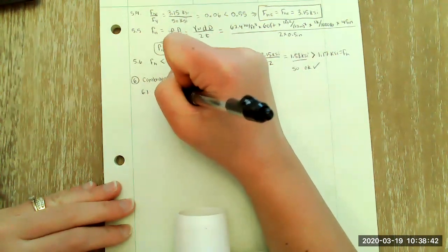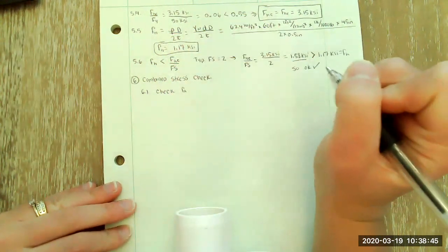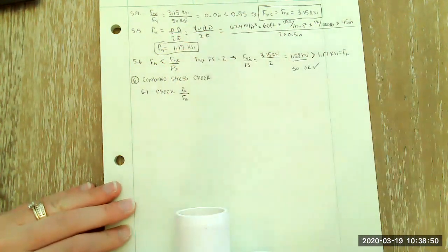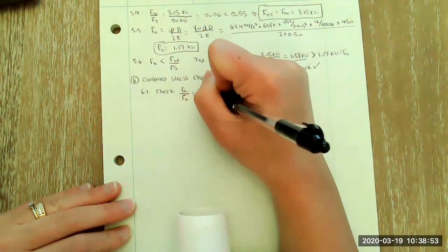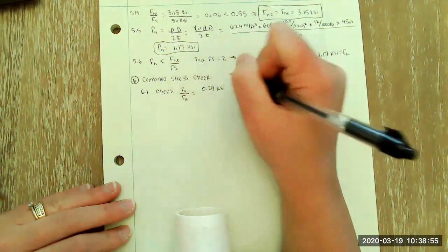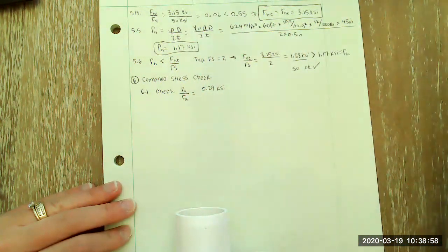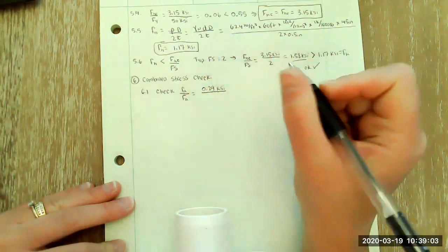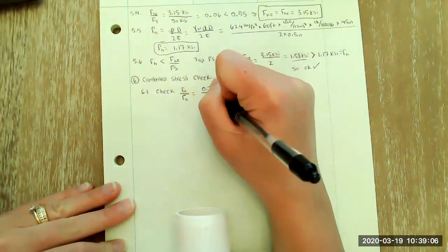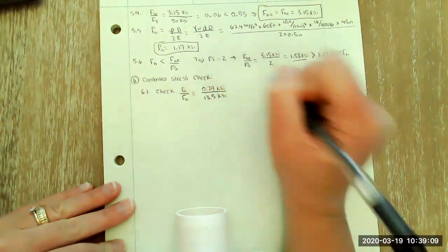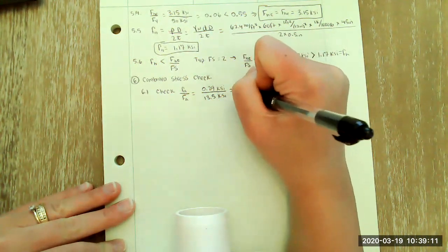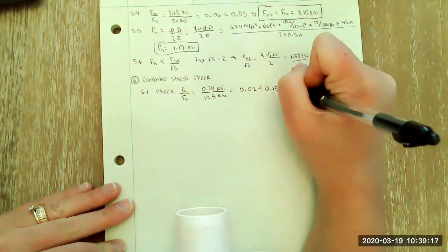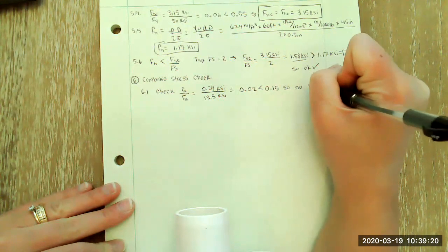So we'll check the ratio of our actual compressive stress of 0.29 KSI to our allowable, capital F sub A. I can go back and double check that from my step 2, my axial compression check. And my allowable is equal to 13.5 KSI. This is equal to 0.02, which is less than 0.15. So we don't expect any P delta effect,